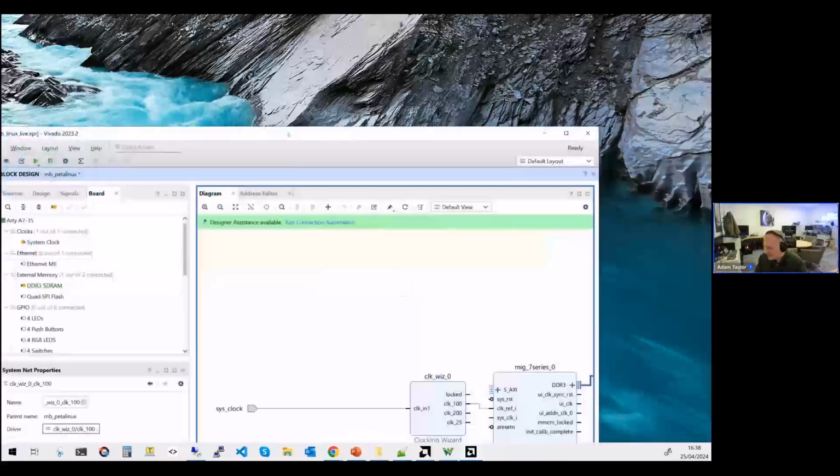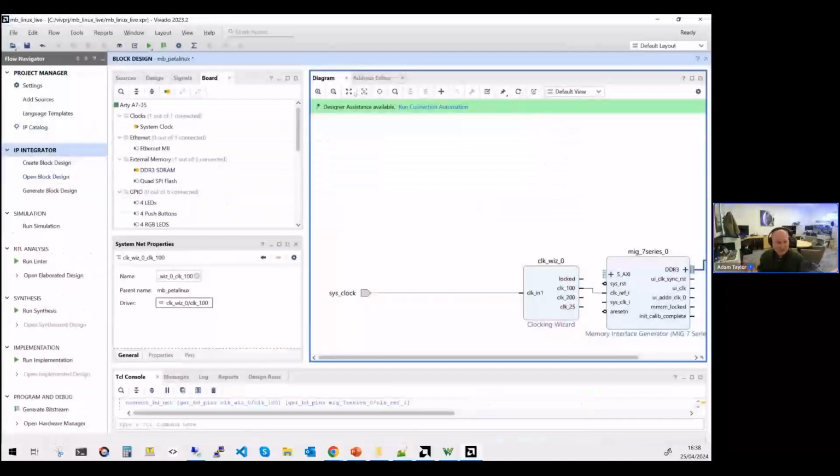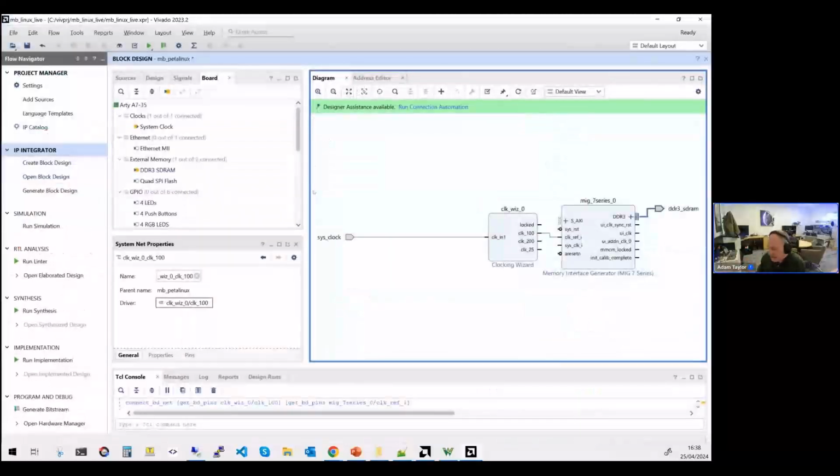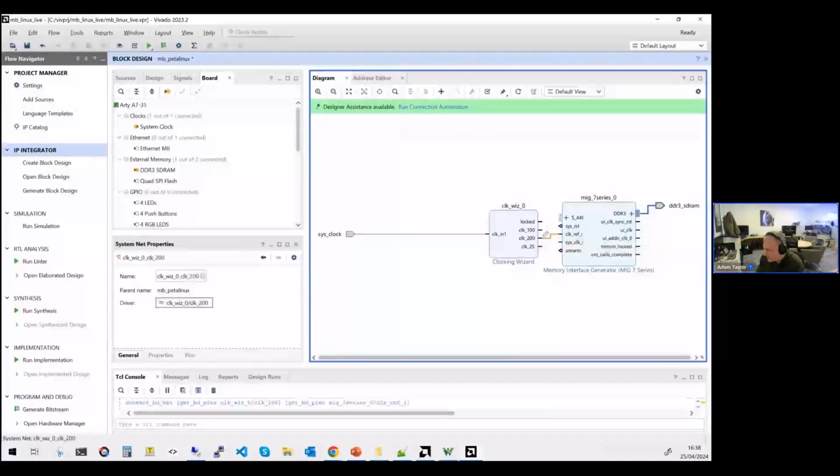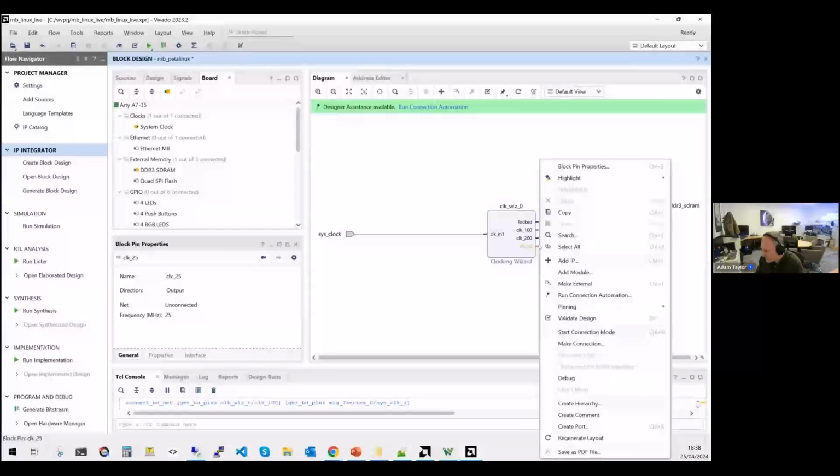Sorry about that, everybody. It's some weird mode in Vivado. I added in a new block, and it worked okay. So the ref clock is 200, the system clock is 100, and we're going to make this one external. I think I've connected those the wrong way around.